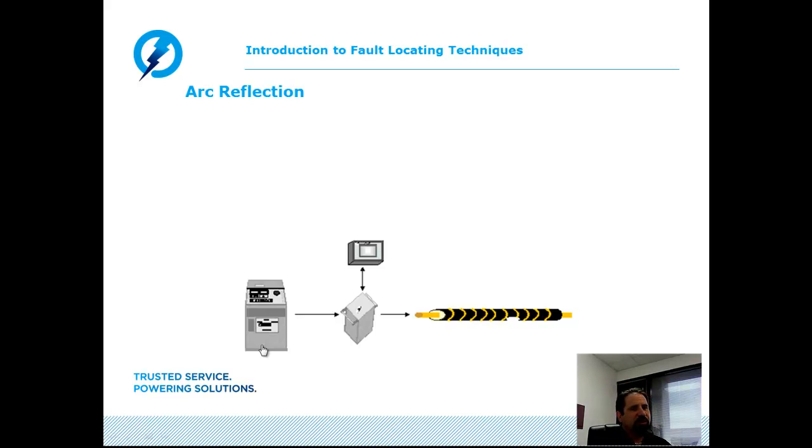Now the reason why we're using a high voltage device is the pulse echo technique by itself is a very good tool for low voltage cable applications, signal control cables, telephony cables, data communication cables, maybe security system cabling. But we do face one problem when we're trying to use the pulse echo technique on medium voltage electrical power cables. Again, these vented trees that form a